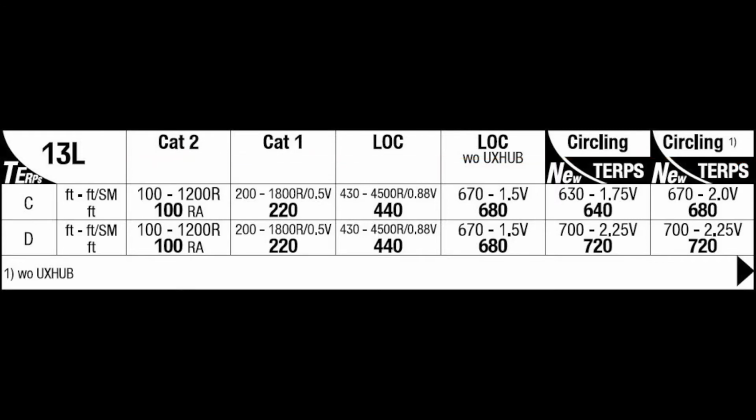Please note that where Cat 3B is possible, the Cat 3A minima are omitted by intention, as long as the Cat 3A approach is to be used with the standard approach minima of down to 0 feet decision height and 200 meters RVR. In the US, 0 feet decision height and 700 feet RVR. Where higher minima have to be applied, these would be shown. Simply apply standard Cat 3A minima as provided in your airline OM-B or AOM for the respective aircraft operated.